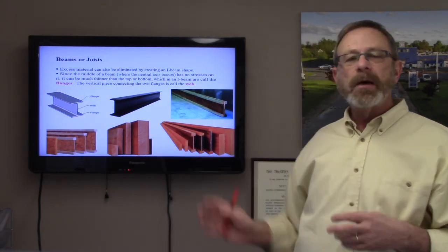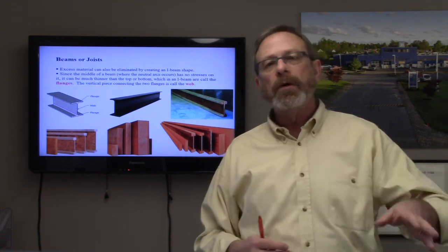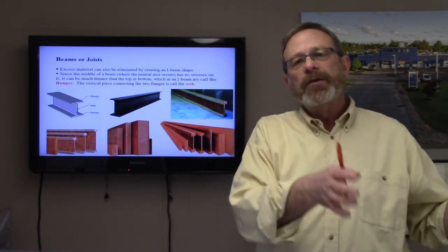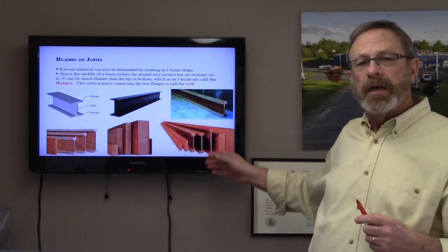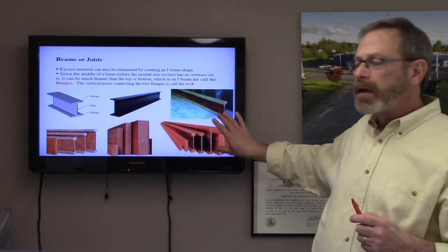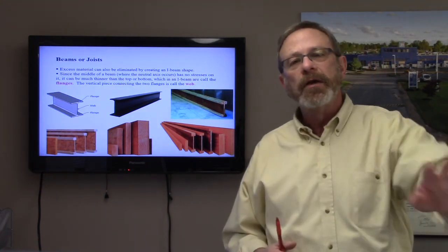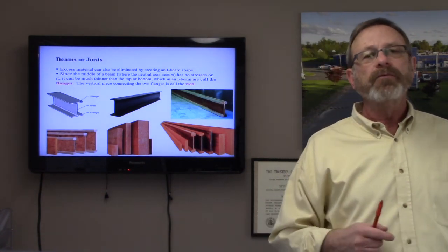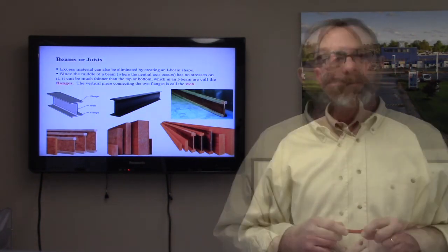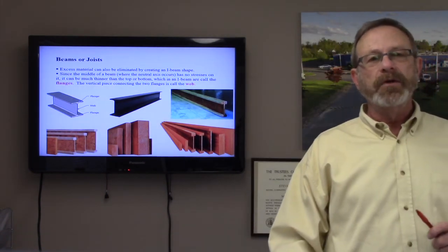And as these flanges got thinner and smaller and stronger, we can now span longer distances. Whereas a big piece of lumber would span maybe 15 feet from wall to wall or wall to column, and we might end up with a column in the middle of our room or in the middle of our basement. Well, with the engineered lumber, a piece of that, perhaps the same depth, can now span 20 feet. So we don't necessarily need an intermediary support. We can have what is called a clear span, whereas previously we might have had something in the center of our room interrupting the open plan.